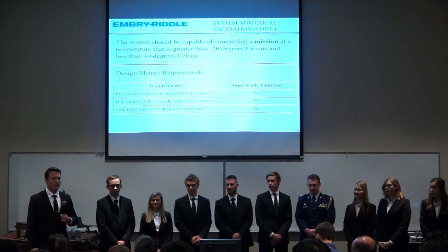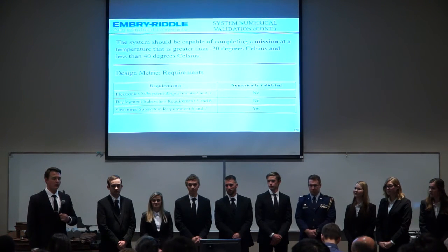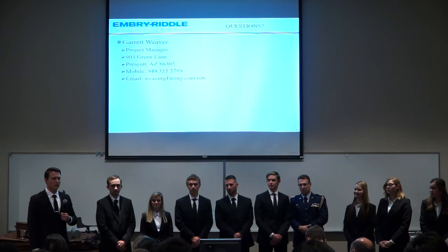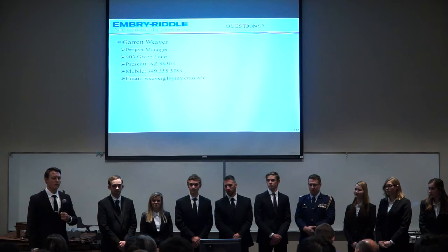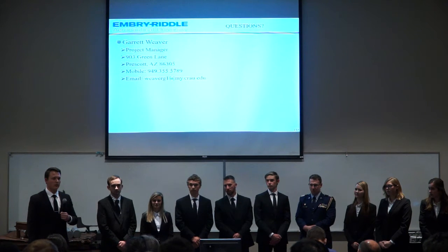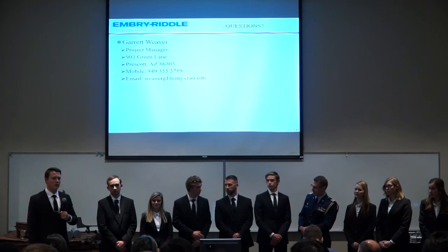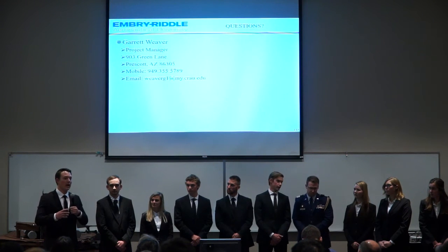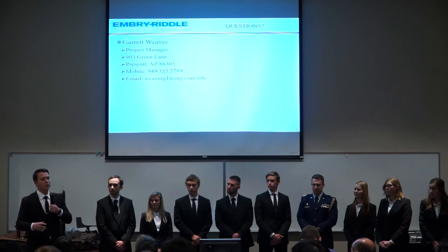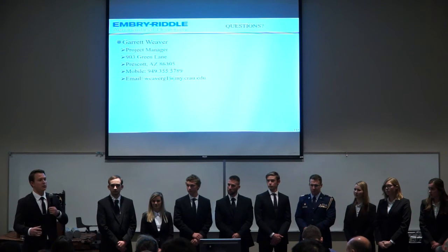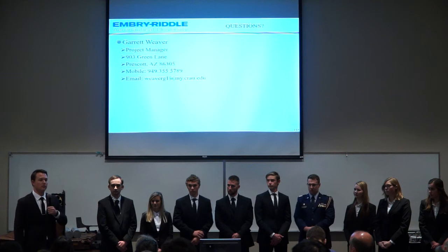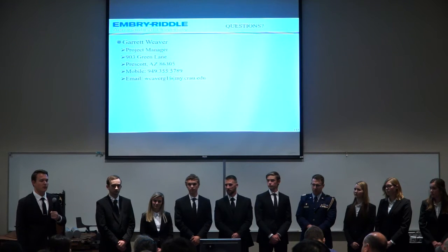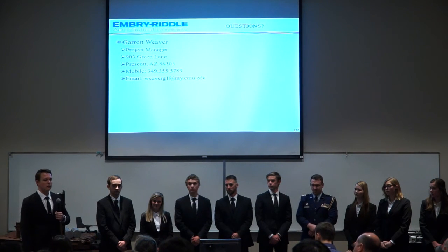Okay, so let's work. A few questions. The first one is in general about safety. You have 1 valve per tank. It would be probably nice to have at least 2 or 3 for redundant safety in terms of releasing the pressure of the tanks if something goes wrong. Each tank will have its own personal solenoid valve that will be responsible for bleeding out if there is an emergency situation where we hit the board switch. It will depressurize all tanks. But I would go with 2 safety solenoids per tank, because if that valve fails, you don't know what to have. Okay, we will look into that.